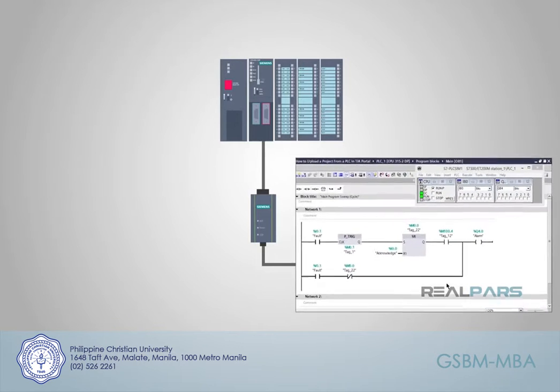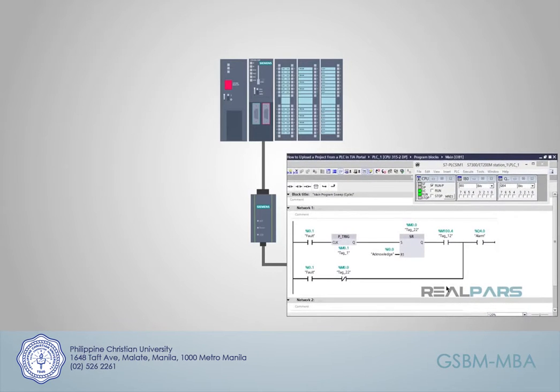Unfortunately, the PLC manufacturers have failed to agree on how we program the control logic. Although most of the manufacturers claim some form of ladder logic, the specifics of that language are different for each manufacturer, including different capabilities, different ways of doing the same thing, and even differences in the order in which the CPU processes the various pieces of logic.